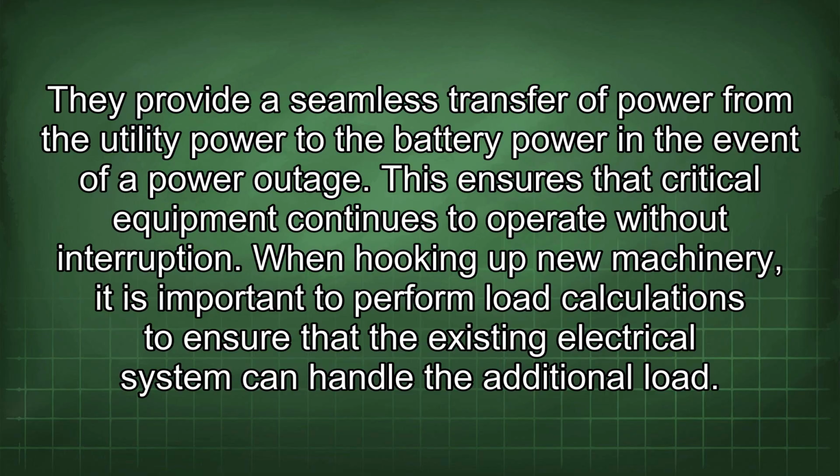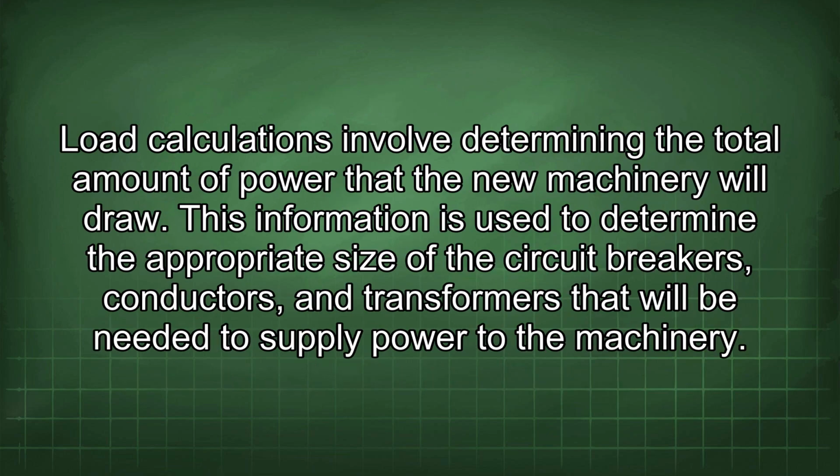When hooking up new machinery, it is important to perform load calculations to ensure that the existing electrical system can handle the additional load. Load calculations involve determining the total amount of power that the new machinery will draw. This information is used to determine the appropriate size of the circuit breakers, conductors, and transformers that will be needed to supply power to the machinery.